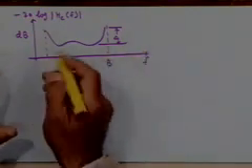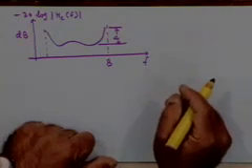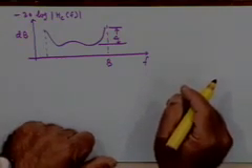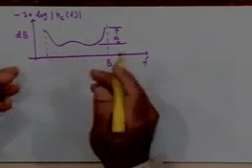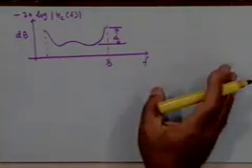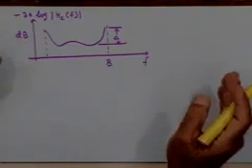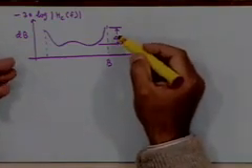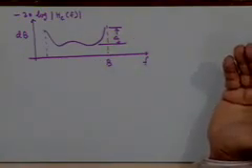I am plotting here only for positive frequencies, you can replicate for the negative frequency axis, okay. And so we are going to see characteristics like this which are not flat, right, which is what you would ideally like to see. As long as this delta is small, overall variation is small, you can ignore it, it does not matter very much, right. What is the extent to which you can tolerate it? When this variation is within a dB or so, within 1 decibel or so, right, that is a rule of thumb for you to remember, right.